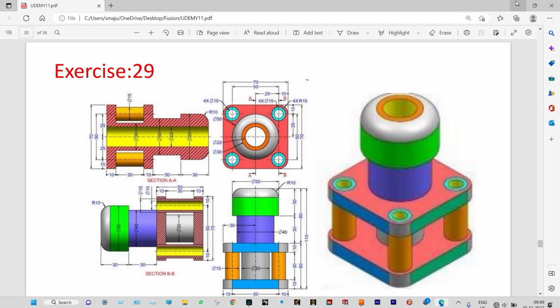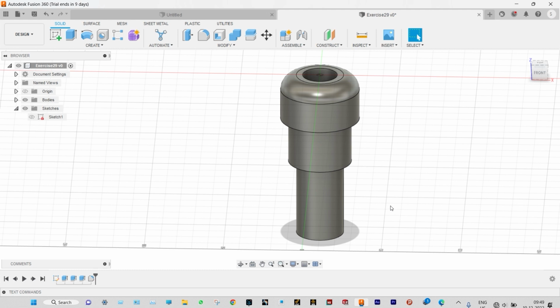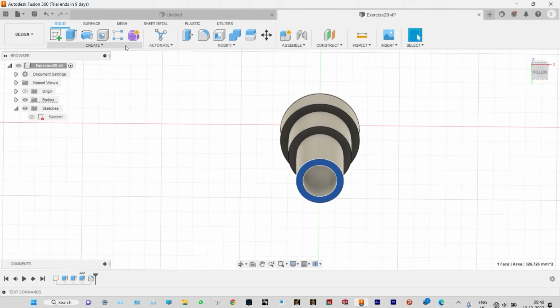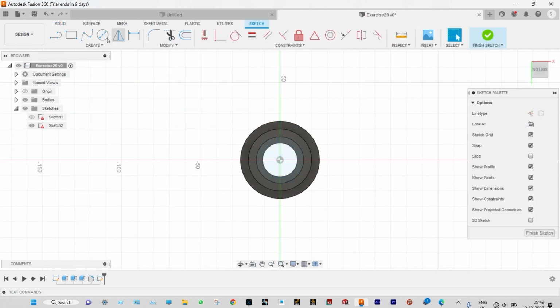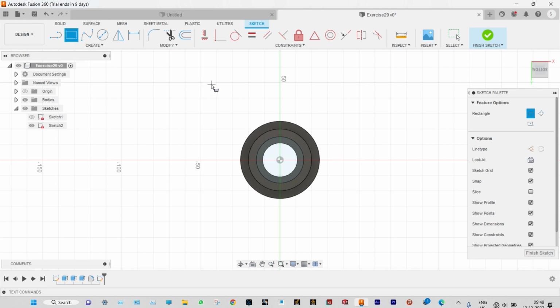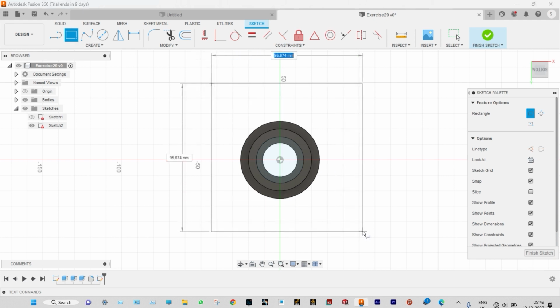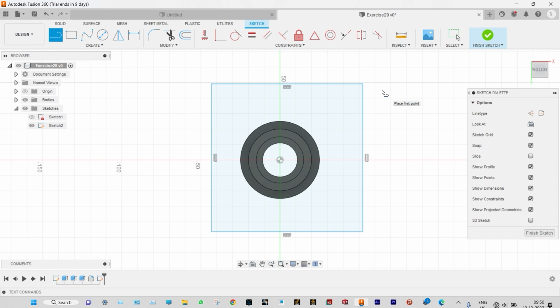Okay, fine. So at the bottom of this pin we need to provide a sketch. So let us select the specific surface. So start sketching on this plane. Initially we'll make any rectangle. This will be arbitrary rectangle, and that to be made symmetric with respect to the central axis. Right, so to make a shortcut line, hit L.